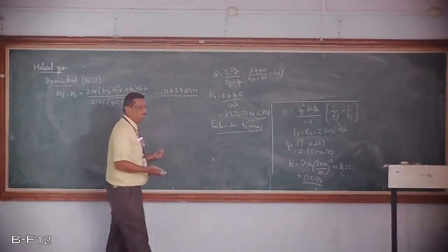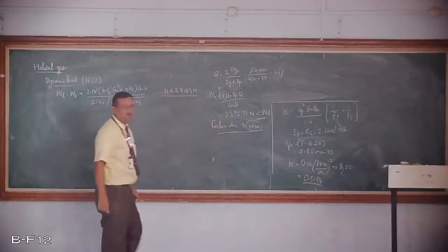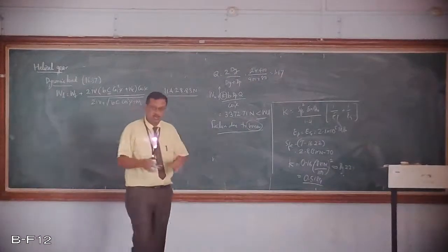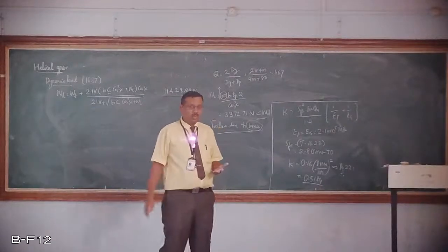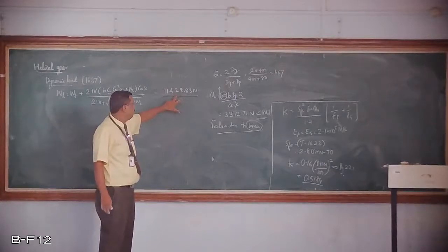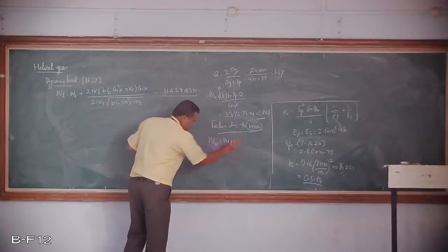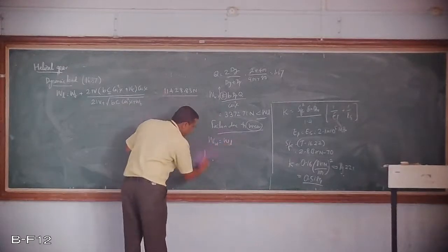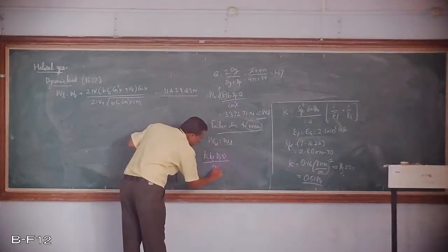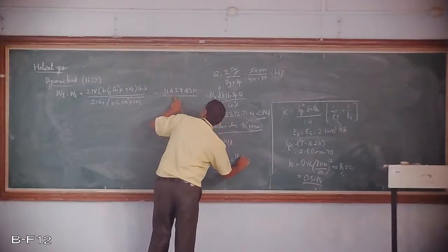Now, when you are increasing hardness, this is the value which deals with the hardness. We have to improve this value of K. What should be the value of K? You can go by trial and error, increasing the hardness and finding out the limiting value. I should get at least this much, 11428. Therefore, we'll equate this wear load to the dynamic load. The wear load K B dP into Q divided by cos square of psi should be equal to the dynamic load, at least 11428.